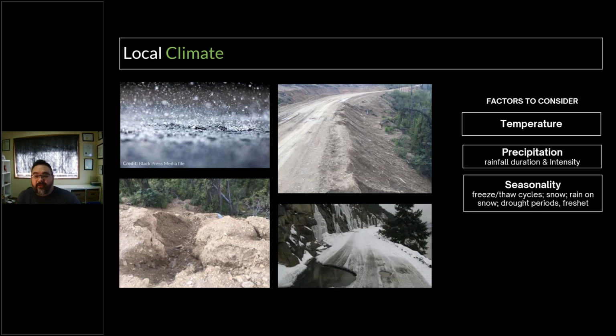And then concentrating drainage, the picture on the bottom left-hand side, that's fill slope erosion in the springtime, where the snowbank has breached in one spot, and now the water's running down the road and finding a hole in the snowbank where it's going to erode the fill.